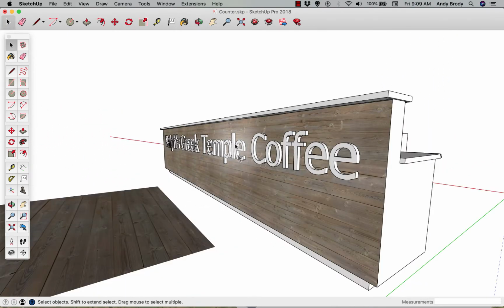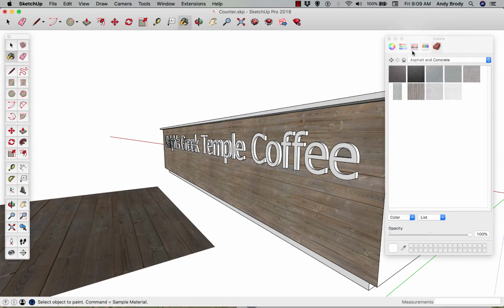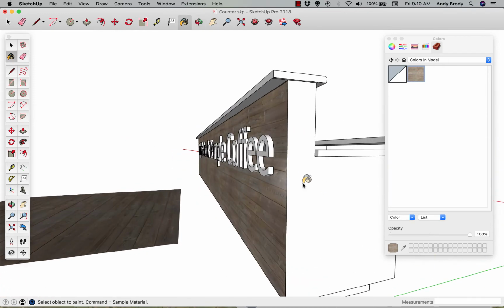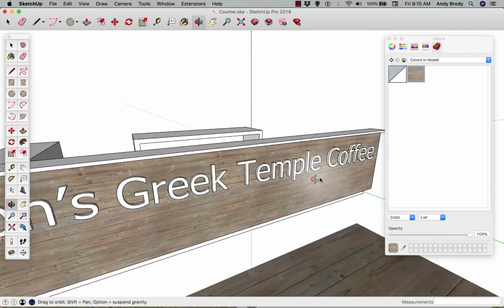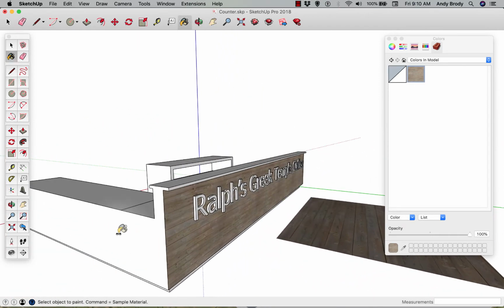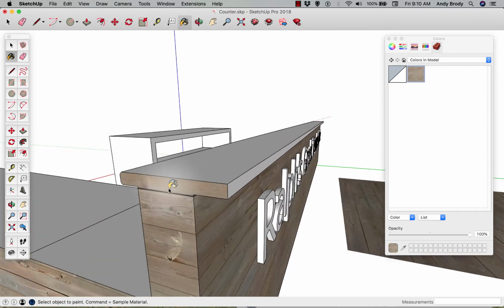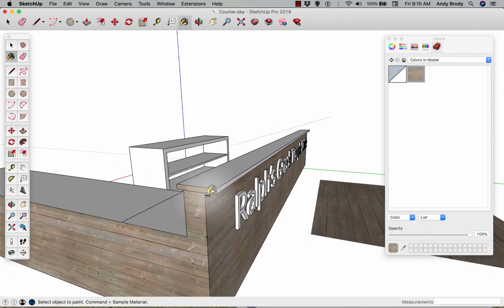How fun is that? Oh, that's really fun. But it's also great because now you can use it as a paint. I'm going to go here. Well, if I just click the home button, you'll see that this paint is available as an option in my used paint button. I can also, if I hold down the command key or alt on a Mac, use an eyedropper to suck up the delicious paint color, and then that will make it the current paint, and I can paint it anywhere I want. So we can do this for any number of custom materials. Obviously, little subtleties like maybe the material doesn't go up here. You'll want to fix that.